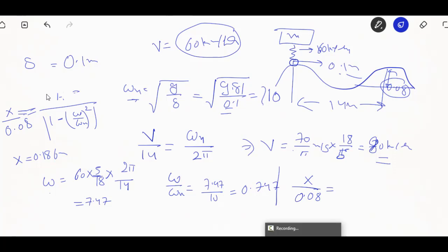Okay, now one more thing in this part is that this frequency that we calculated here is the natural frequency of the system, which gives us a speed of 80 km per hour. Now, if we see the lighter bikes or car, which has been designed to run at a speed of 100 km per hour, it is the maximum speed of a particular vehicle, let us say, but we cannot drive it at this speed. It will start vibrating abruptly and ultimately result in any kind of failure.